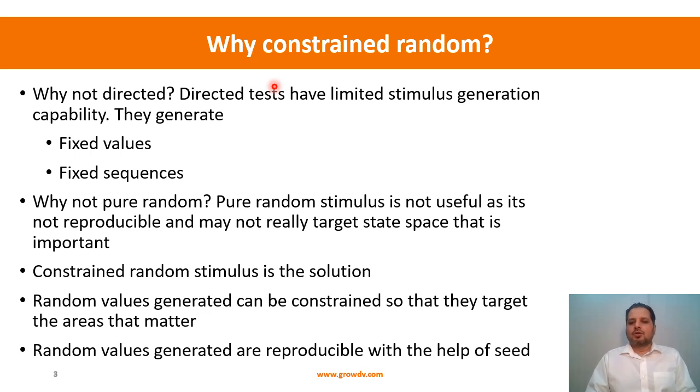Let's take a simple example. I could have a USB port and I want to test a scenario where the port enters a low power state. Let's say I've connected a mouse or a USB flash drive and I'm not using it, and I want it to enter a low power state and see how that behaves. So I can write a simple directed test case. I'll do some traffic, make the port enter the low power state, wait for some time, cause some event to come out of the low power state, and then do some more traffic.